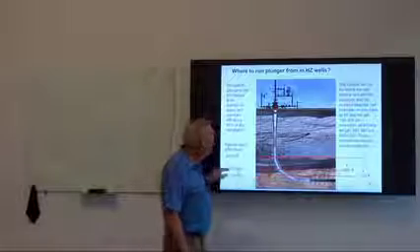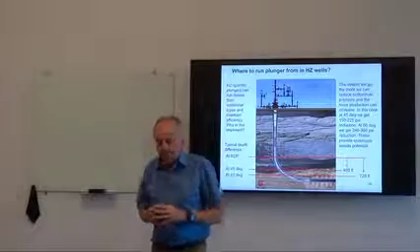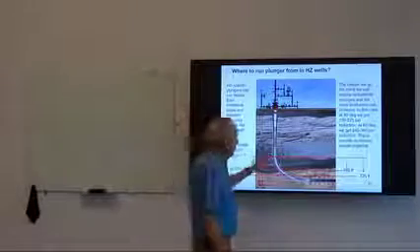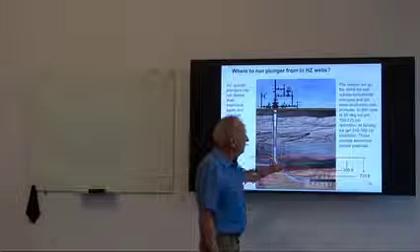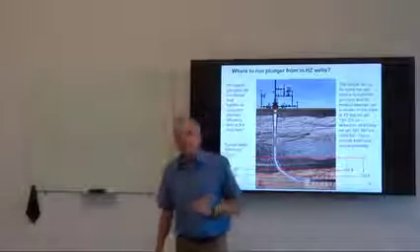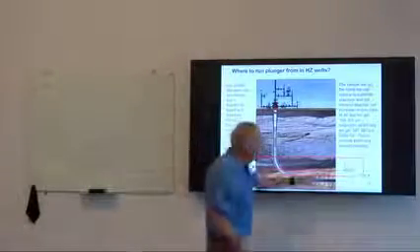So at 45 degrees, for example, and this is from a very typical drilling survey I got these figures from, at 45 degrees in this case, there's a 450-foot TVD difference from the point at which we can remove liquid. And our perfs are down here.